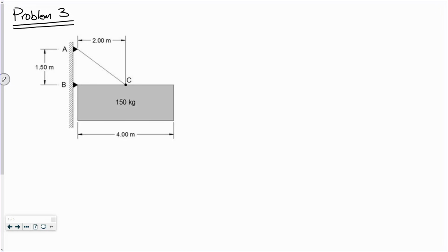If you're going through and doing the statics, you might take the weight of that sign as 150, and there's probably in those A, B, C, D choices a choice that is off by a factor of about 9.81. See what I mean? So it's something to think about. It's a very cheap trick to make, but it is easy to deal with.